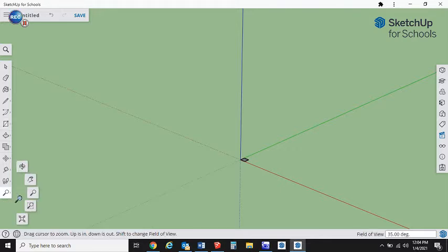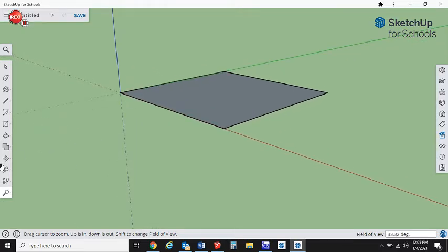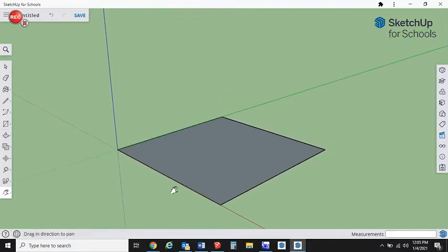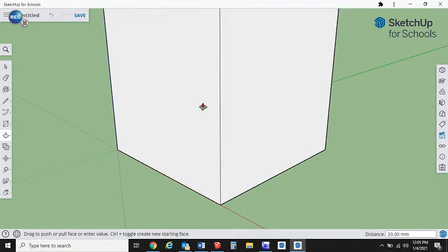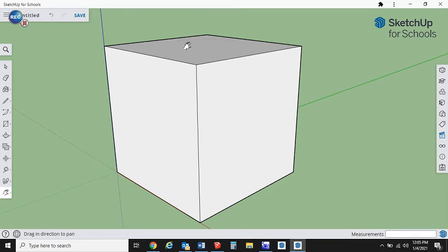Easier way then is to, of course, go with our zoom extents. So there's our zoom extents. We're going to now drag that up. Let's keep rolling here. H, we're going to pan that down. So H is for the hand or the pan tool. Okay, and then P for push pull. So we click, release, drag. We're going to type in 20, enter. Okay, then we're going to go back to our zoom extents, make sure everything looks proportionate. So 20 by 20 by 20.